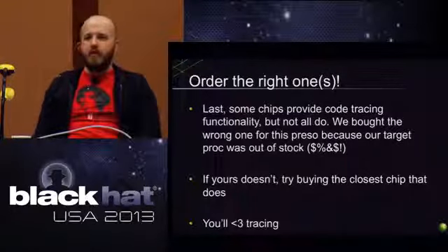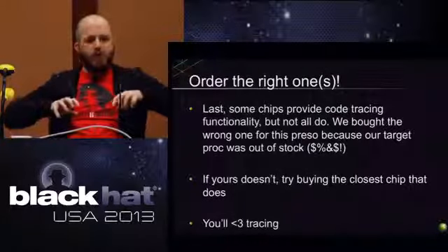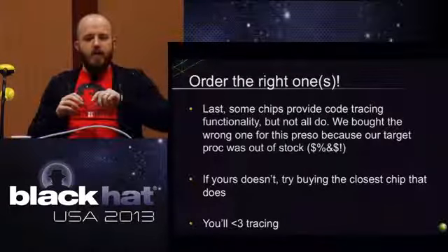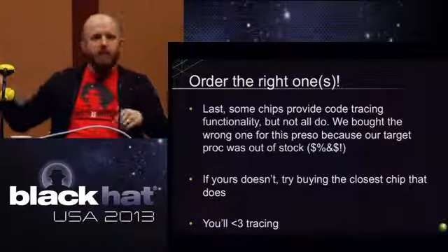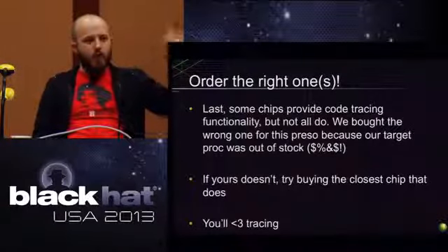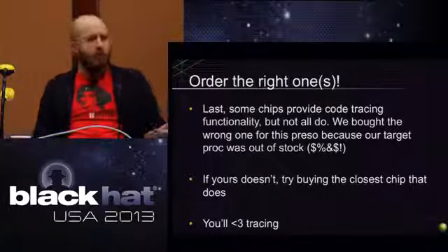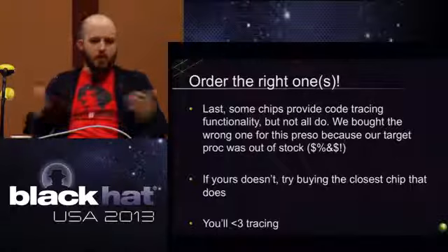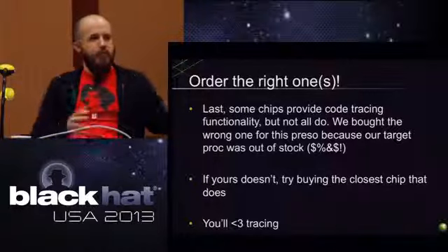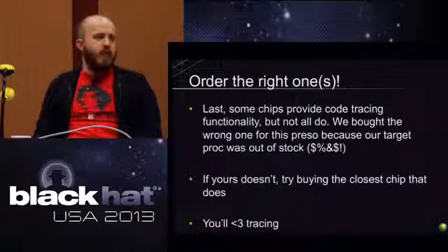And code tracing is basically what it sounds like, right? It exports the full state of all the registers at every single cycle. So the debug application that they use gives you the ability to go backwards and forwards through execution state as the program's running. It makes it so much easier to figure out what's going on. If you're trying to figure out exploitation, or how it's pulling in and decrypting a certain part of itself to pull keys out, it's so much easier if you have code tracing.